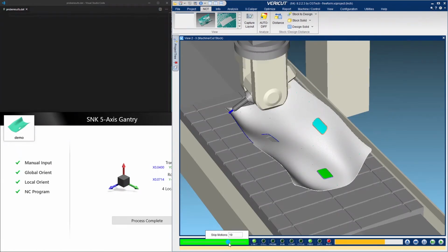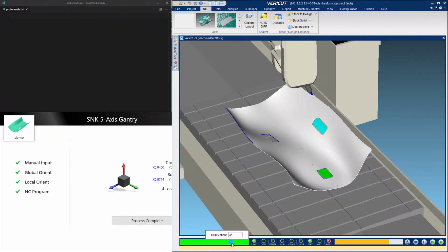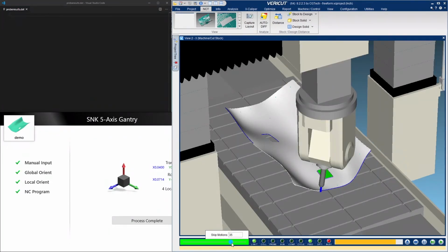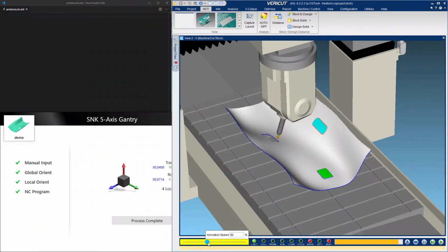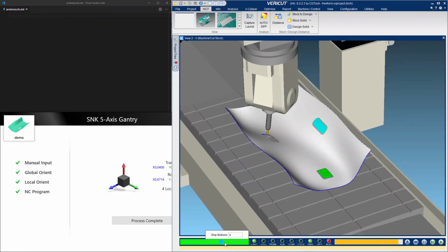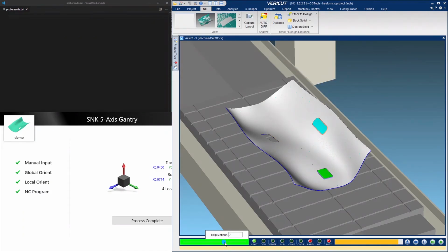Finish the periphery of the part. Again, a full 5-axis operation. And then lastly will be the chamfer tool to cut the chamfer around the pocket. We'll perform now an auto diff on this. And if everything went well, if we set everything up correctly, we will see nothing but white on the part, indicating that the part location and part surfaces were transformed correctly.